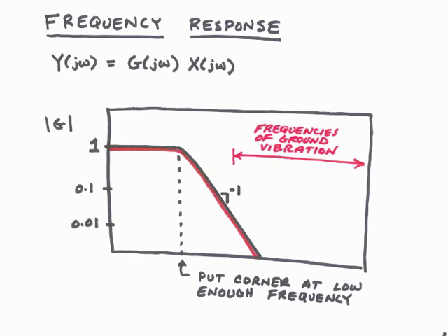That corner frequency is essentially the natural frequency of the system, omega n, which is the square root of k over m. We're limited in terms of how small k can be made. Typically these tables, the k is achieved by sort of an air or pneumatic system. And it can be low, but to get k very low, what we need to do is to make the table massive, to increase m, and that will lower the natural frequency of the system, lowering the corner frequency here, and yielding greater vibration isolation at the frequencies of the disturbance.